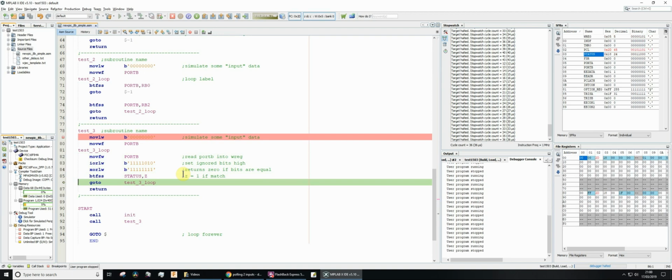Now, this time, let's modify port B. So we give it the data which we're actually looking for, which the least significant bits are going to be 1, 0, 1. So that's a bit pattern that we're going to look for, because remember I said the zeros represent the bits which we're interested in, and then the ones represent the values that I'm actually after.